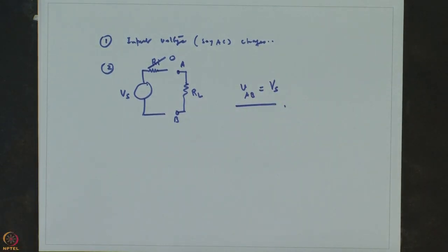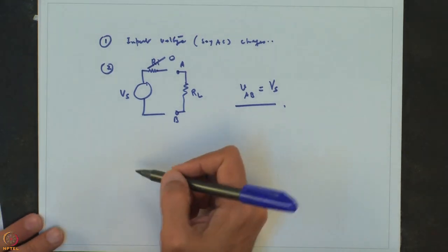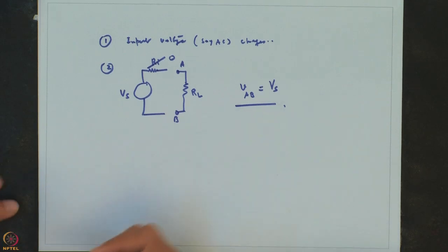But this kind of ideality rarely happens. So, if you actually try to equate the power electronic circuit which is giving out a certain voltage output which you want to apply to a load RL, there will be several drops in the circuit. As we just saw, the inductors and the capacitors will have parasitic unwanted resistances which will cause voltage drops, and similarly there will be devices which are also going to cause losses and drops.